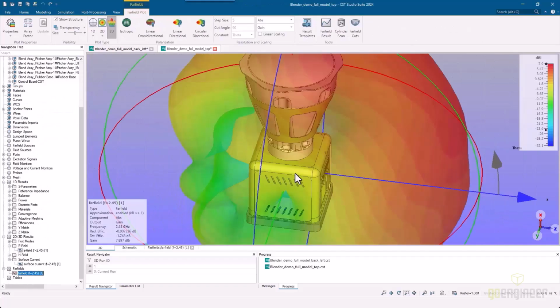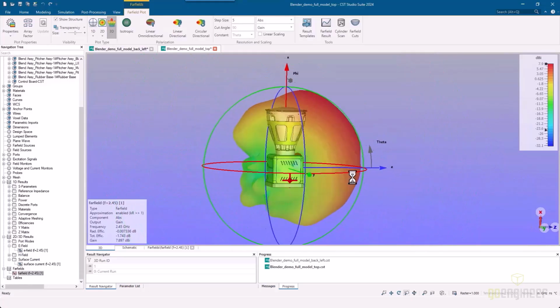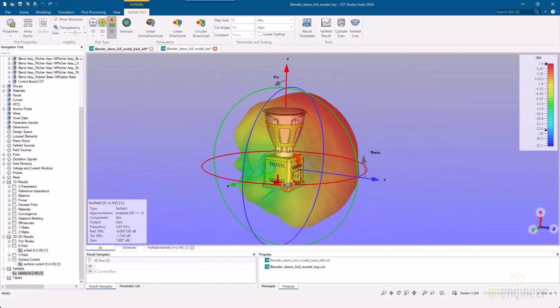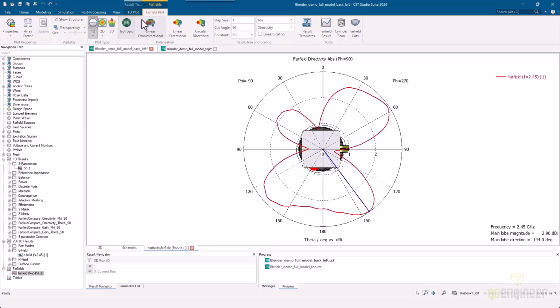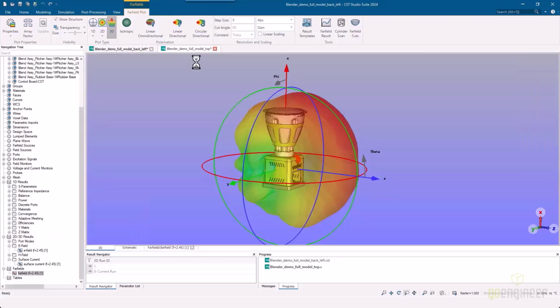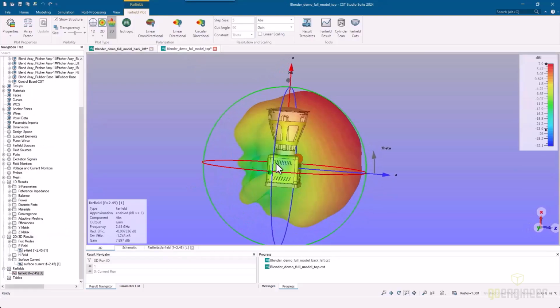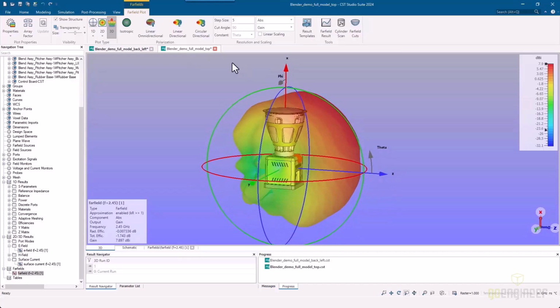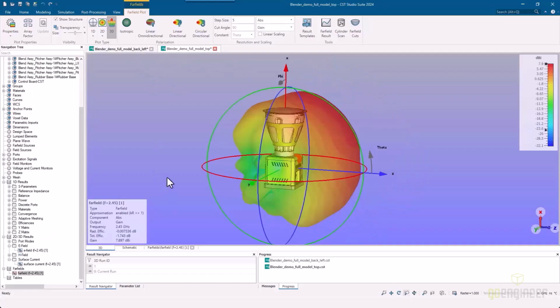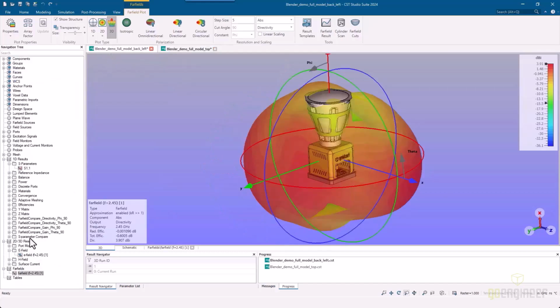If we take a look, this is for the antenna at the top. You can see the bulk of that near field antenna propagation was to the front of that model. Here, this is with the antenna on the back looking at the near field, and it's a nice bubble in and around. Again, the horizontal top antenna is all to the front of the blender, where previously with it vertical, it's wrapping around the blender itself. So this is a lot better propagation for the antenna signal, and Clint proved that very quickly to me using CST Studio Suite.